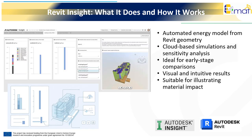Revit Insight is Autodesk's internal tool for early-stage energy analysis. It extracts geometry and basic material information directly from the BIM model and generates an energy model automatically. One of its strongest advantages is speed. It allows users to compare different design options and observe how insulation, glazing type, orientation, infiltration, or shading affect overall building performance.